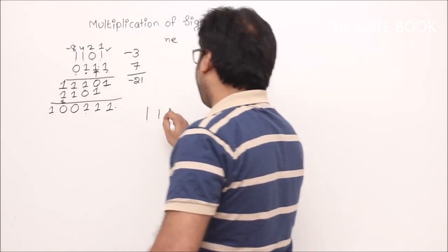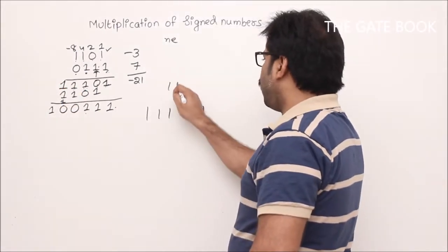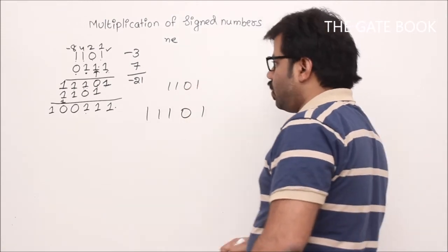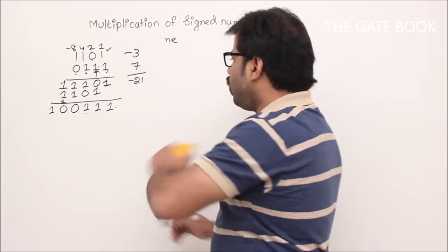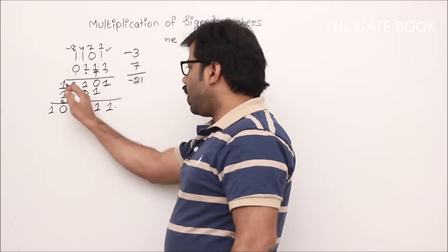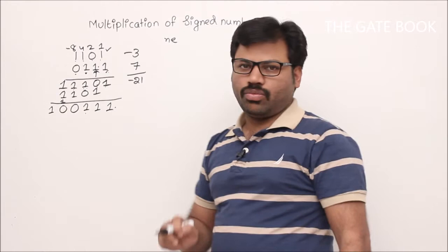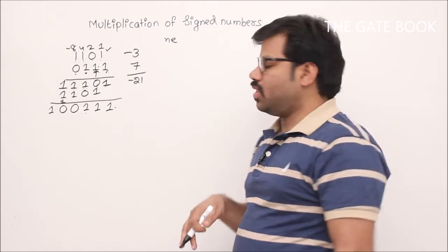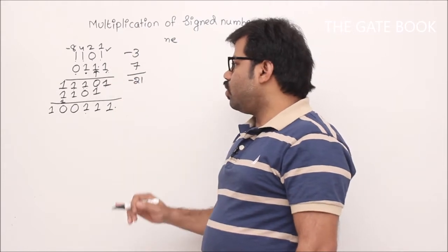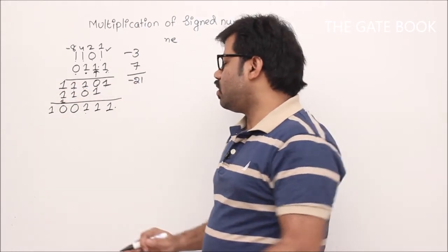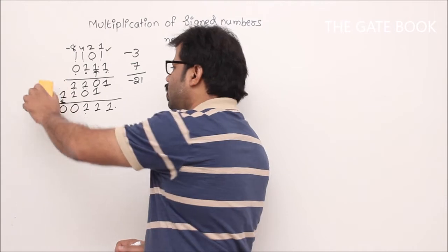Now if I write 11101 instead of 1101, both are the same, you see, correct? So always remember, whenever you shift right, then we have to add 1 rather than 0, because now it is signed multiplication. So when the multiplicand is a negative number, what do you have to do? You have to extend the sign bit. So this idea is now simple from now onwards.